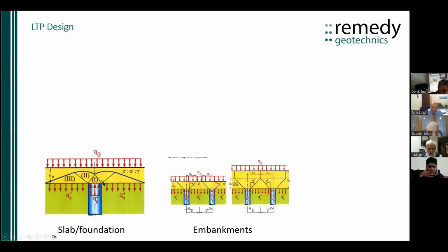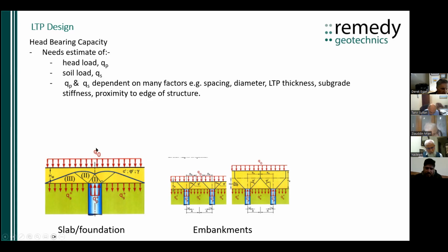Providing this material is thick enough, you can have your Prandtl failure curve set up where the column is punching that way, and the resistance to a bearing capacity failure emerging within the column is a function of the resistance of the ground there and the load within the column there.